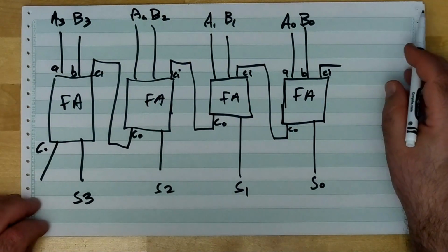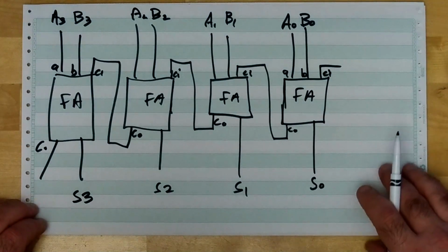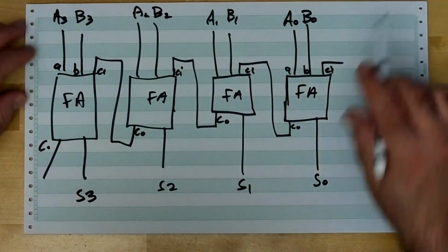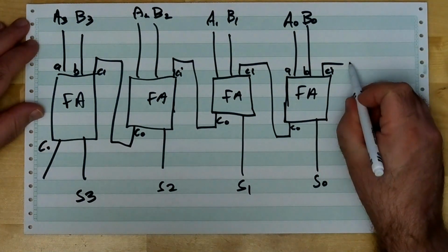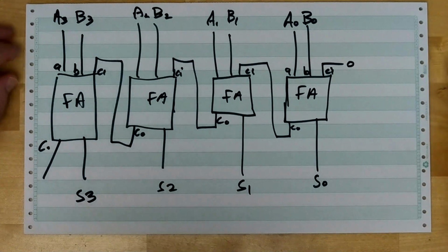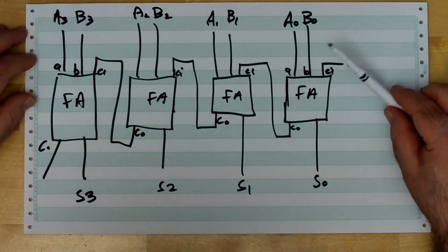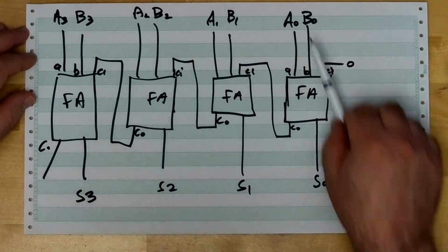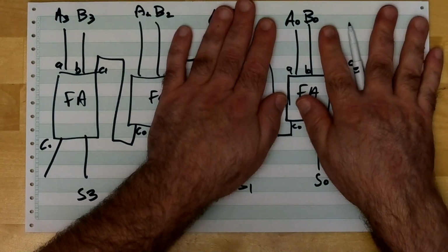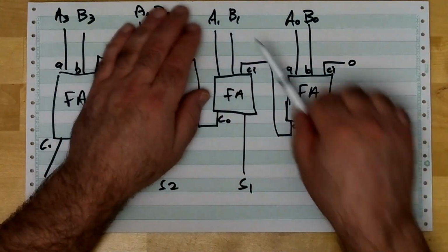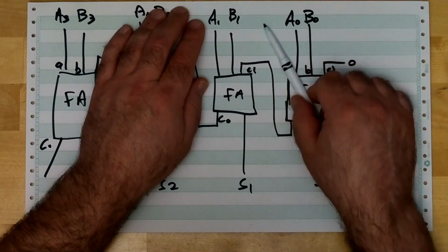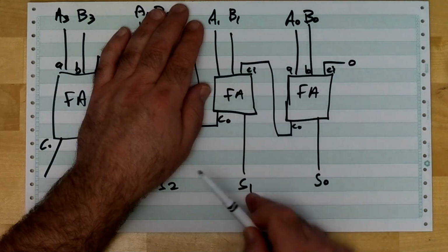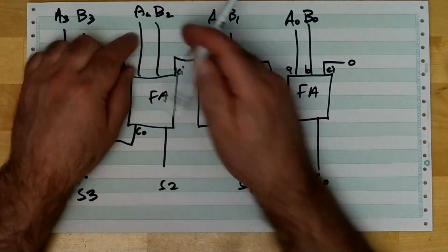And remember, we used to play games with this carry in the far right column also sometimes, right? That had to do with subtracting. We'll get there soon enough. For now, let's just set it to 0, okay? So, what does this then mean? If that's a full adder and we're going to add A to B, get the sum of these two bits, we get a sum and a carry. We can then add the next column of bits for A and B and the carry that propagated from the prior column. Get the output there and the carry, right?